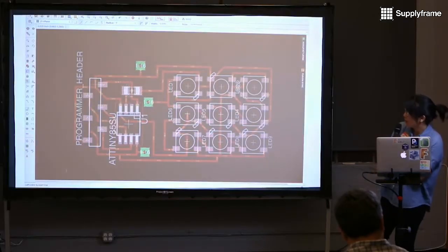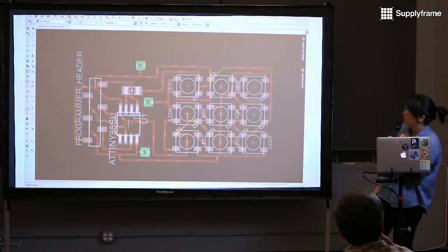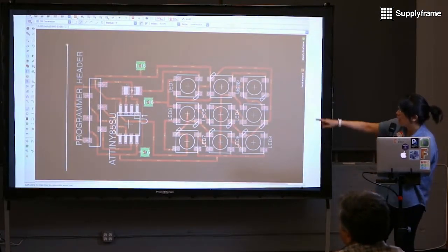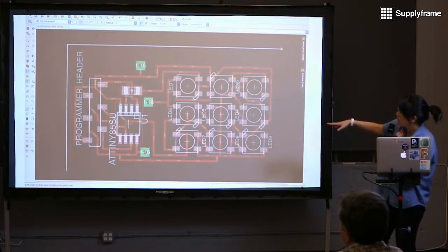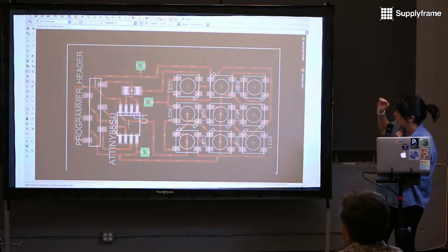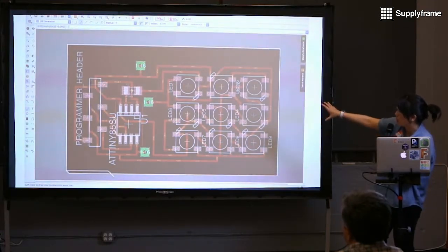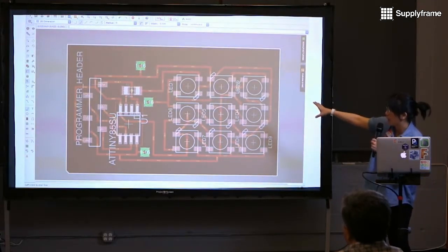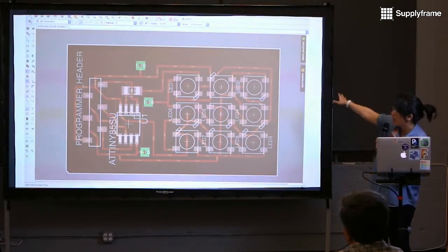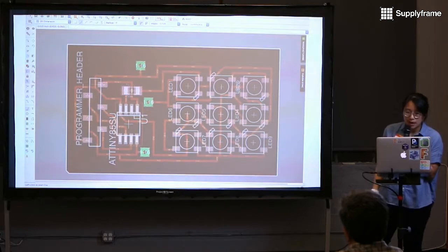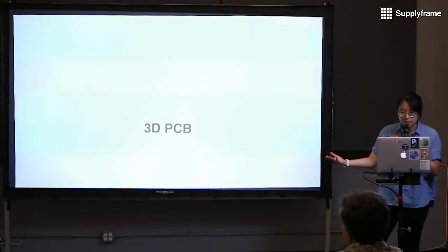So basically what we did is, this is actually far more interesting from a technical standpoint, I guess, than a UI standpoint, but now when you actually draw your board outline in Eagle in the dimension layer, you'll see visually, once it detects a closed contour, it'll change the color of the board to let you know, okay, this is the board outline we've detected, and then the editor background is a different color to improve the contrast. So that was really important as another step to help generate a 3D PCB.